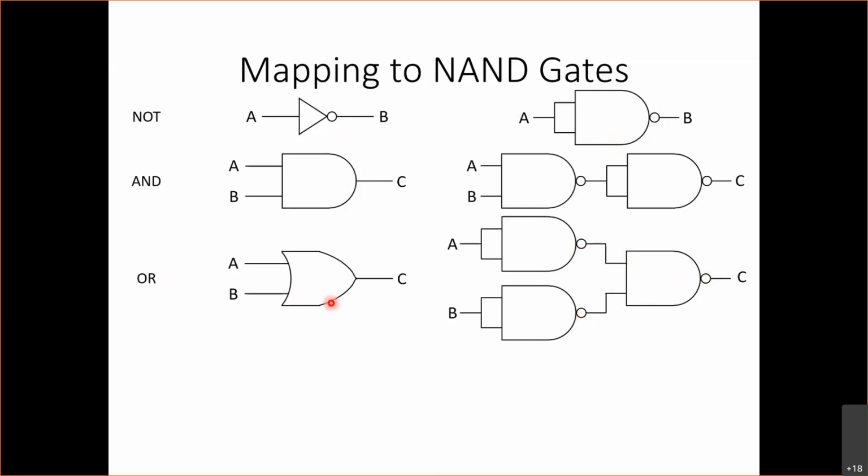Okay. When we were in class, it was much easier to explain why these two are equivalent on the board, because you can kind of erase things and redraw things. But if you replace this NAND gate over here with an OR gate that has inverted inputs, you can see that if you put an inverter here and an inverter here, they cancel out the inverters over here, so this over here becomes equivalent to an OR gate.